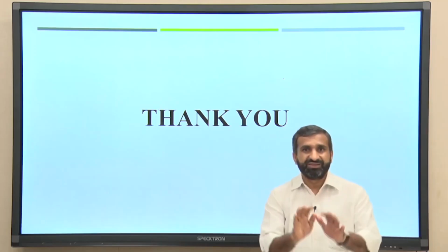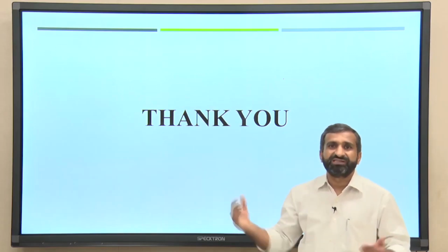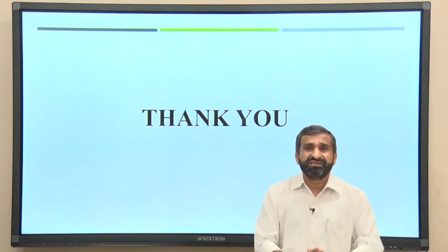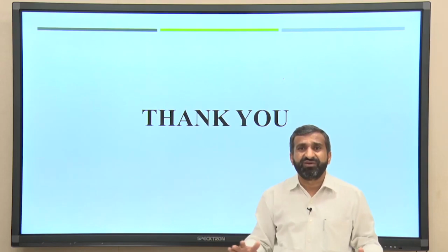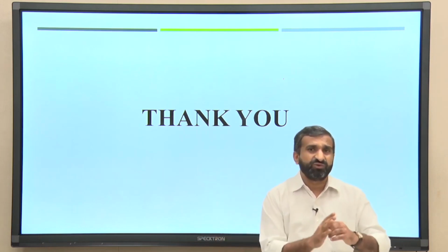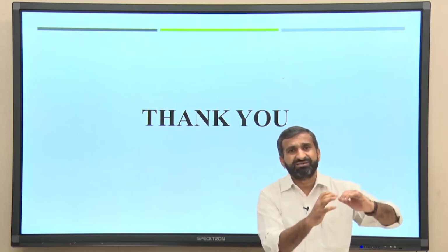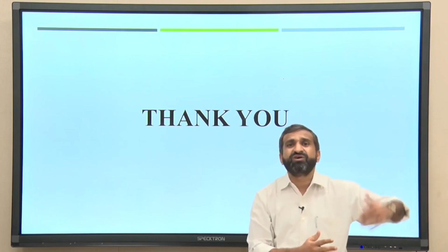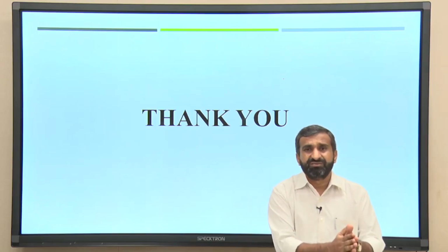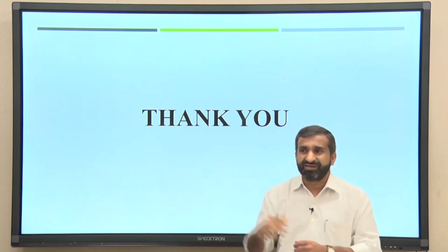Now, in this lecture I talked about two ways we can have the hydrolysis process: one is the pretreatment process and the other is the co-digestion process. If you compare both techniques, it again depends upon the local conditions. If in the local conditions a large variety of organic matters is available, then I believe co-digestion will be more beneficial. In some locations only one particular kind of waste is available for anaerobic digestion, so in that case plan for some mechanical pretreatment process. Based on local conditions and waste availability, we can go for either monodigestion with mechanical pretreatment or co-digestion with the different organic matters available in the local area.